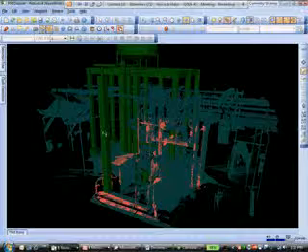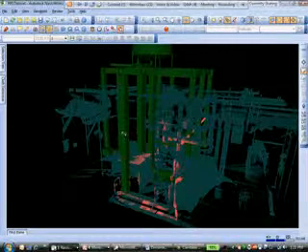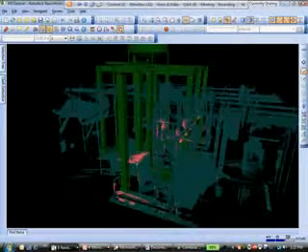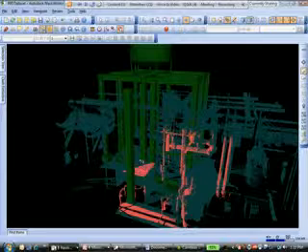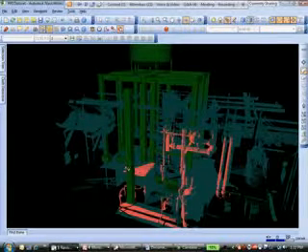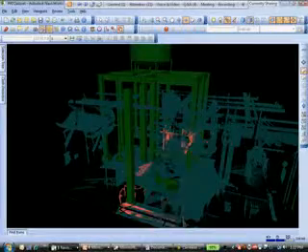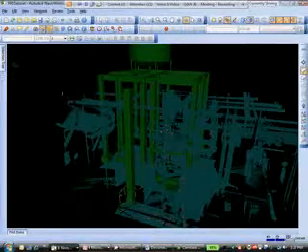One of the things that Navisworks does very effectively is manage external data, and we've seen this in the case of bringing in different model types, but we can also link out to external databases. One of the more common ways of doing this is when we link out to a scheduling application like Primavera or Microsoft Project. We can link in those start and end dates, and then using one of the Timeliner features in Navisworks, we can go back and sequence these activities. But one of the other options we have is to link out to an Oracle type database or Microsoft SQL Server. Leveraging this information, we can now use this model more from an asset management and, like I said, even a facilities tool.